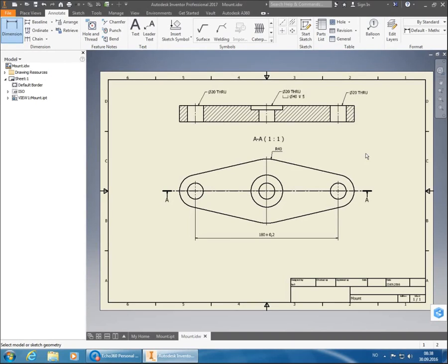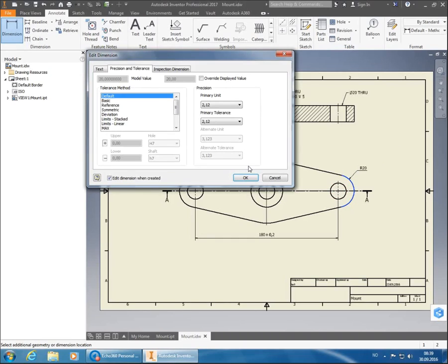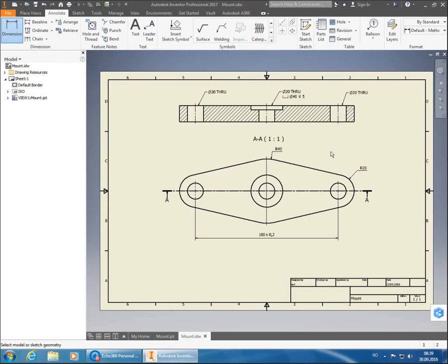The same goes for the curve on the edge here. We put in R20 there, and it's symmetrical across the center, so it shouldn't be necessary to put in typical or a dimension on the other side. Then one more thing that we can do, just to make it a bit easier to read the drawing for whoever's going to create it, is to give the total length. I missed it there. Let's see.